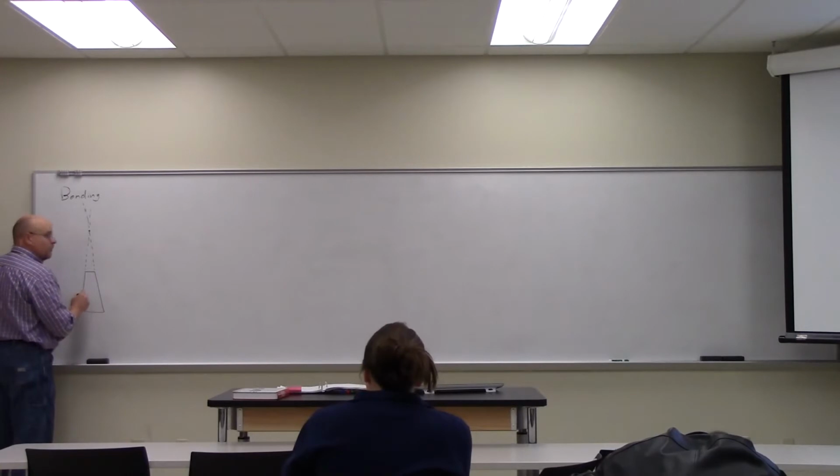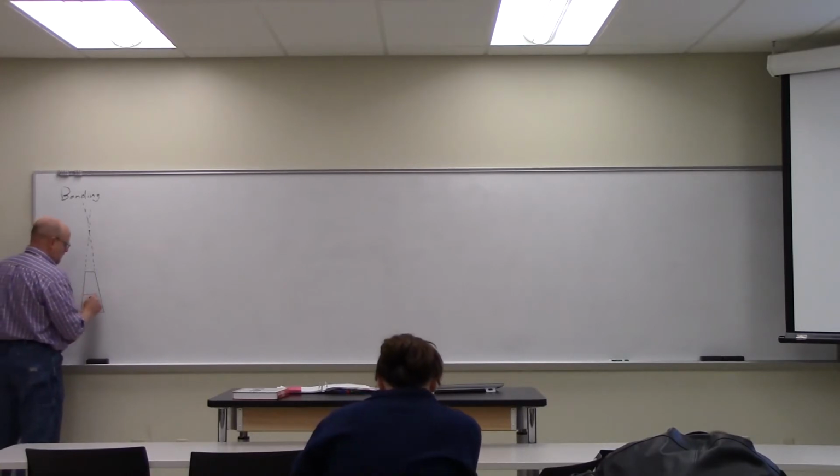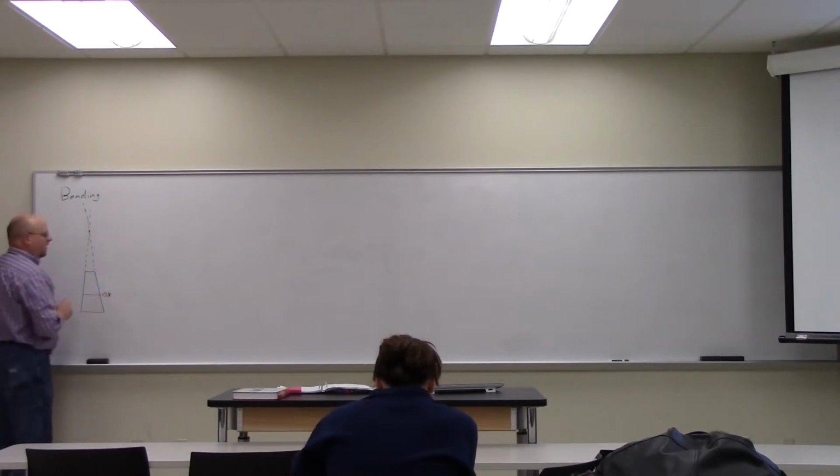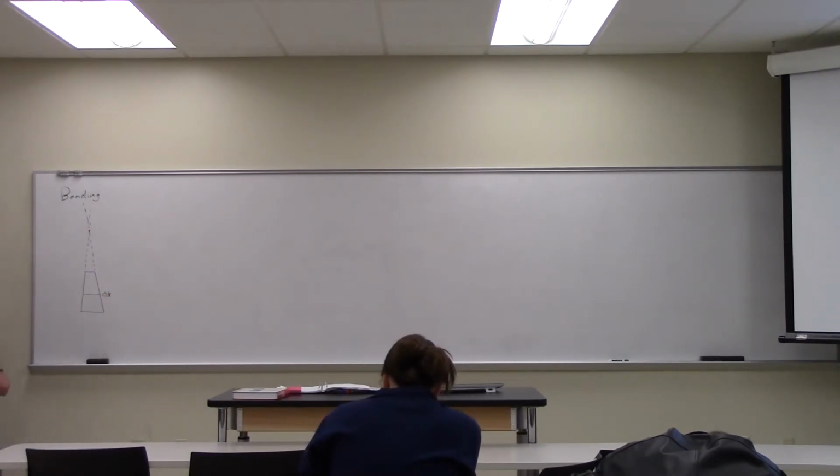All right, so there's some middle plane here in which the width, delta x, is the same as it was before it was deformed. Right, so there's some plane. If I bend this thing around, I stretch the outside, I compress the inside, but there's some plane in the middle where there's no stretch of any kind. No stretch, no tension or compression.